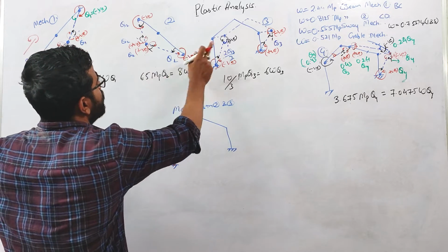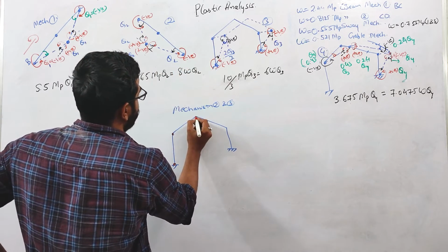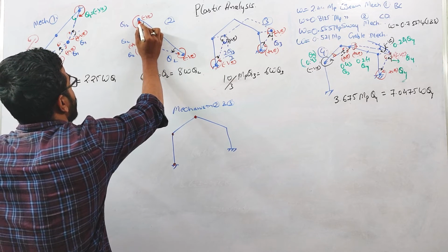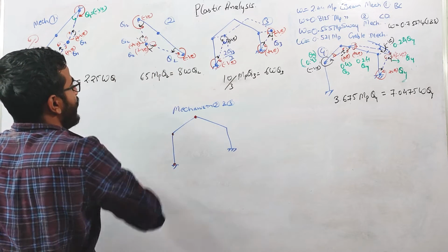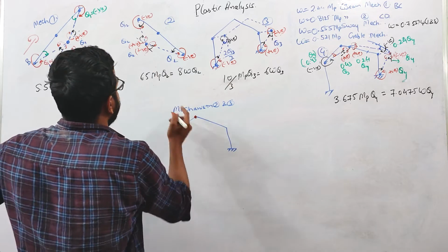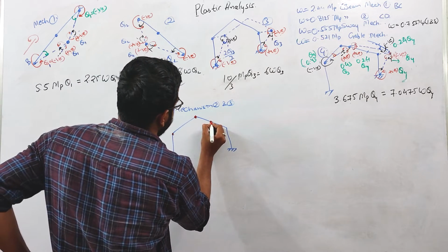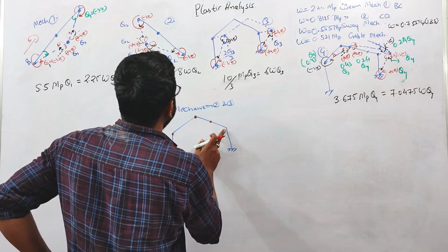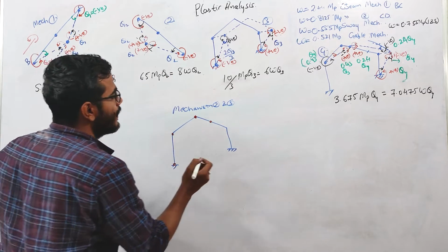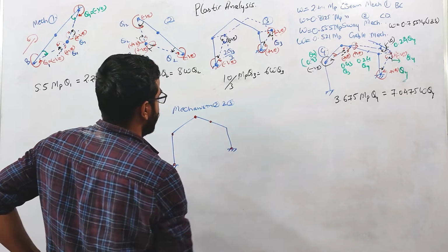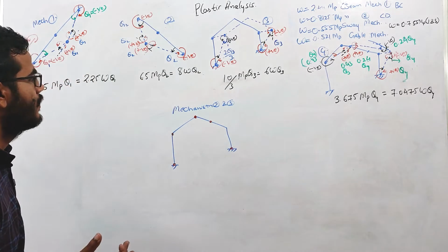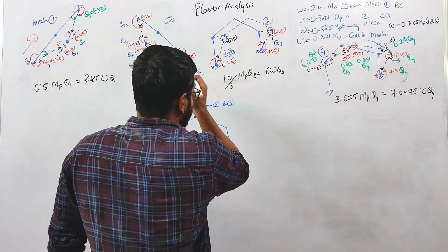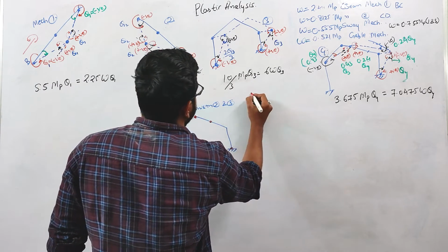Now, if you combine these two, again the plastic hinge will form at this C point, because at C the plastic hinge is forming in the beam mechanism, right? Similarly, at this point also there will be a plastic hinge. We can only cancel this hinge, but it is not possible, because here you can see that theta 2 is negative.